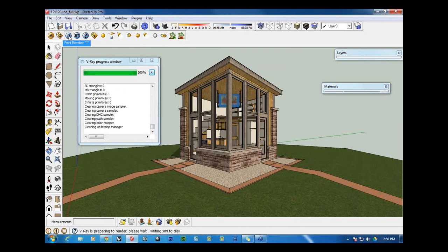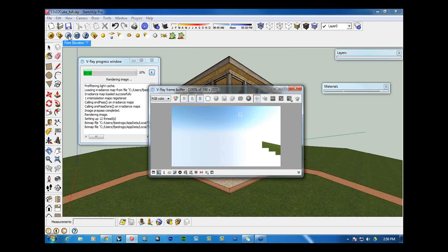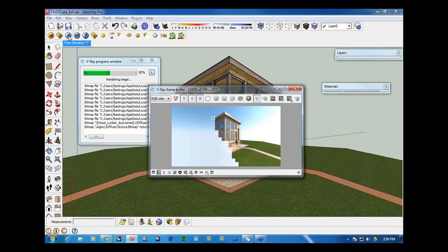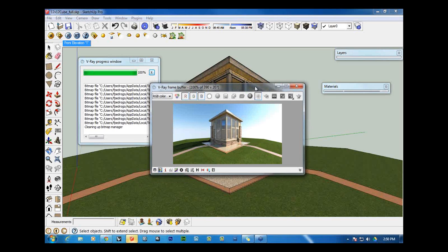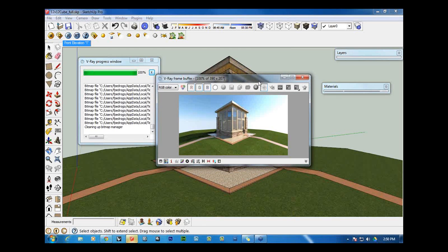So I was saying that for every single bucket, V-Ray will call the proxy geometry only for those buckets, making the loading process and the proxy a very efficient way to save RAM. You could load millions and millions of polygons in your scene, and you will not have a crash due to running out of RAM. So it's a very efficient way to dynamically load and unload models or geometry from your render. I'm going to explain that in an example.